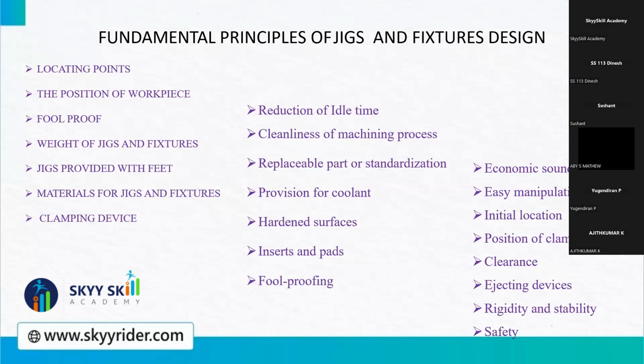And more important, for making any design, clamping and locating are the major factors. Clamping and locating, because locating is your job and clamping is where and how to clamp that component. As I told you, it should be as simple as possible without sacrificing effectiveness. And the strength of the clamp should be such that it not only holds the workpiece firmly, but is also important.